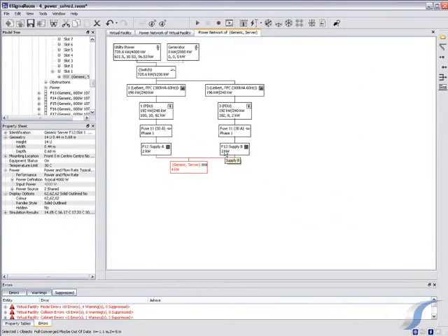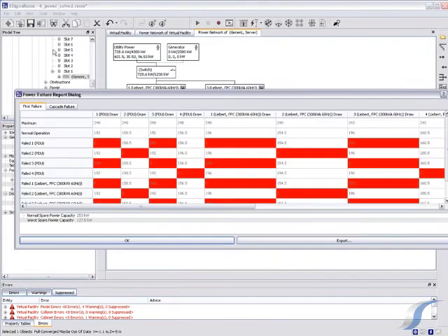Switching supplies should allow the server to survive this kind of failure. However, it's necessary to review the whole room to make sure this would be the case. To do that, we can open the Analyze Power Failure tool. This tool shows us a matrix of how the IT equipment would be left unpowered in the event of a power failure somewhere in the room.